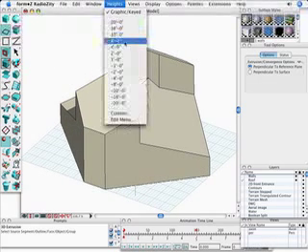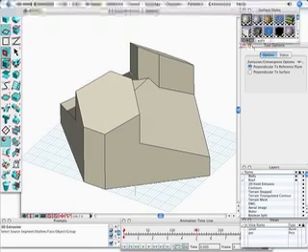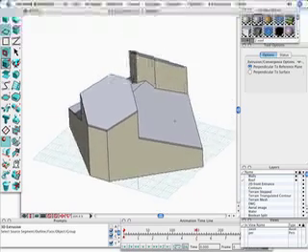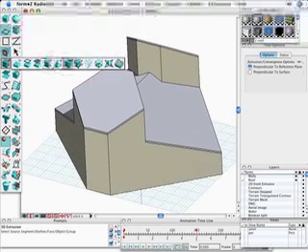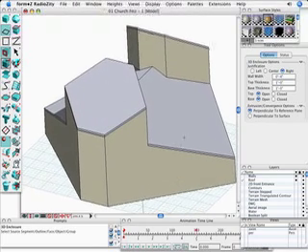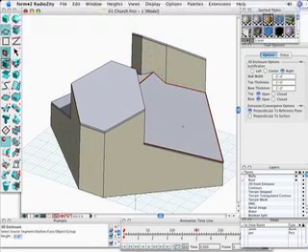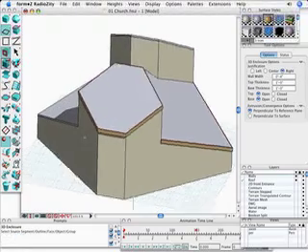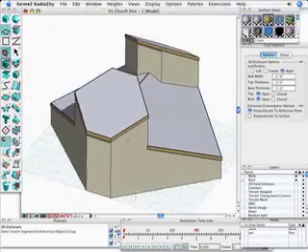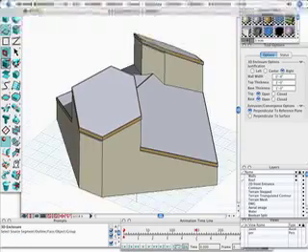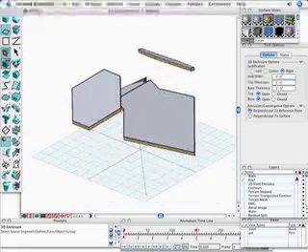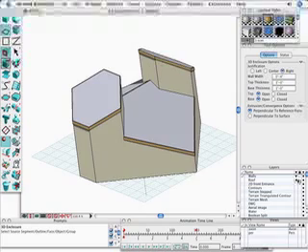At this point, let's create the actual roof itself by using the derivative tools. We'll extrude a 1-foot slab off of the existing faces that are there, so we don't have to trace over any of our geometry. We can use the derivative tools and derive objects from the existing object that's already there. We can also create a 3D enclosure by simply clicking on the face, give it the wall width and thickness that we want, and now we have a nice little 4-inch frame. And there's the roof.